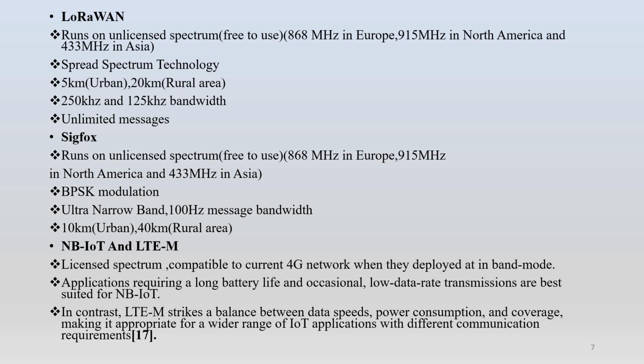It is an unlicensed, low power and inexpensive wireless network based on ISM standard. Initially Sigfox only supported communication from end nodes to base station, or the uplink, using BPSK modulation. So the BPSK modulation utilizes 1 Hz to transmit 1 bps, and hence Sigfox uses 100 Hz frequency to broadcast 100 bps. It has a coverage of 10 km in urban areas and 40 km in rural areas.